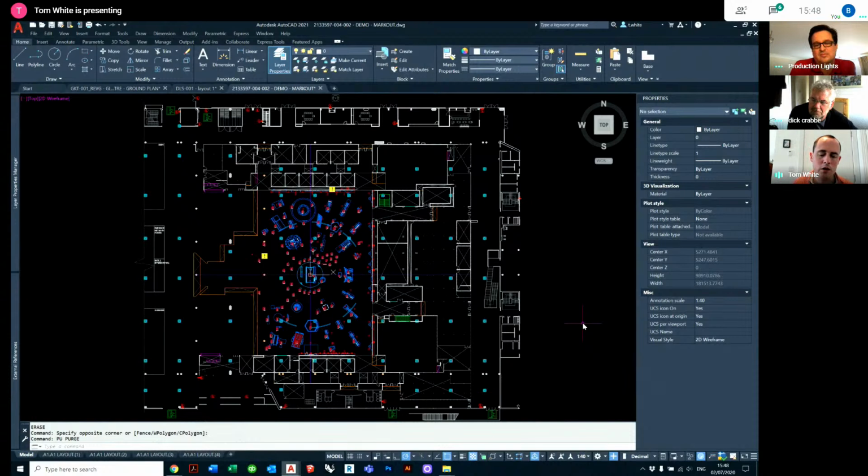And that's in comparison to purging a drawing that's just come in, that's 25 megabytes. I don't think it's an unsafe thing to do. And as somebody who sends plans back to Tom and Dom, in DraftSight it's called Clean, and I thoroughly recommend it, because you watch the file sizes just go from megs down to kilobytes. Which means it's easier to email to one another, or even as a user to open and close.